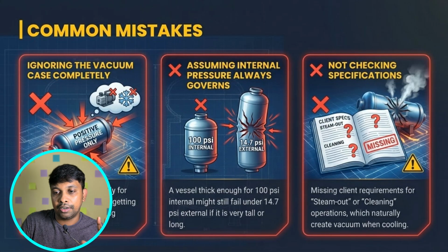Sometimes these details are missed out in the specification, but as a design engineer you have to know that if the vessel is connected with a pump, whether on the drain, the suction or the discharge, then you have to consider a partial vacuum and design the vessel for the external conditions also. Sometimes it will be missed out in the specifications. Sometimes the client or EPC company doesn't know about that. As a mechanical engineer, as a static equipment engineer, that is our duty, we have to do that.